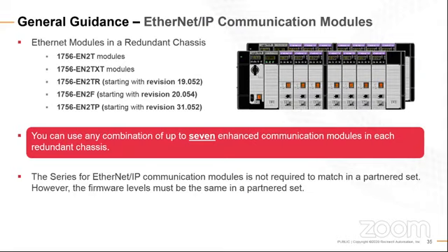As with anything, especially when we introduce the L8 in the first place, one of the things I would always tell you guys is you can support an L8 and an L7 on the same system. So just be aware that as we start doing phase migrations and modernization of systems, we have the ability of essentially upgrading the top end design and slowly phasing everything that we have underneath it. It may require additional controllers.